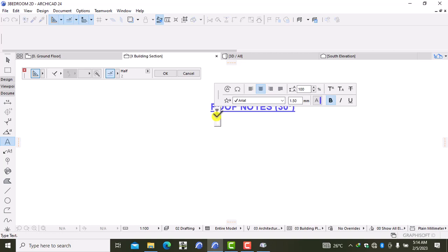So that's 30 degrees. And then the next thing we can now do is get maybe the size of the purlins, the size of the rafters. So we're going to use roofing sheets. So you go ahead and say roofing sheets on 25 by 50 millimeters purlins.